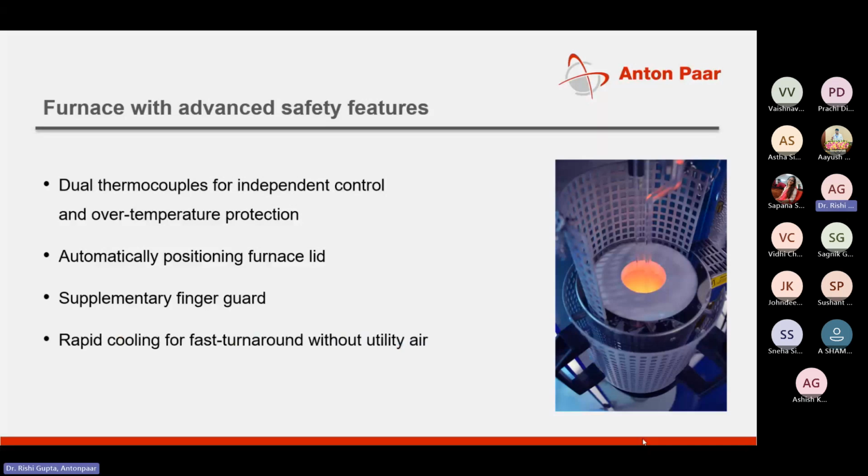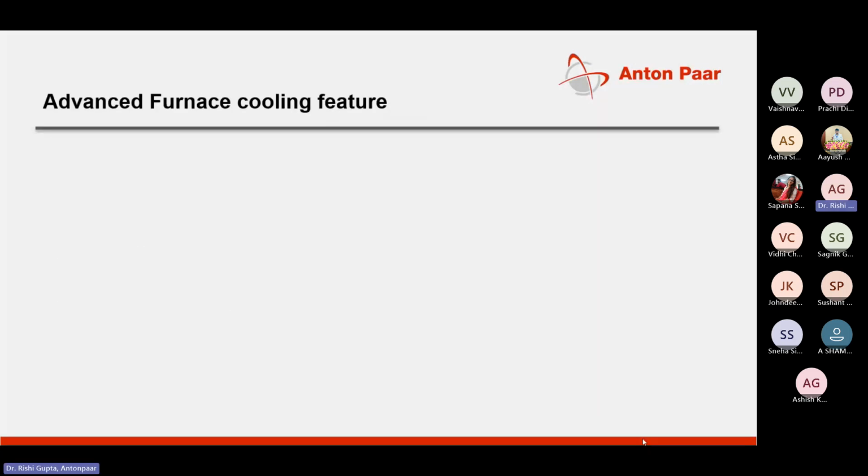The cooling air facility here in this case for Chemisorption is within the machine itself. At the base of it, where you keep the dewar, there is a flap, and if you remove this flap, you will find that there are vent holes over there, and these vent holes are basically for cooling the sample. We already have an inbuilt air cooling facility. So we have a fan over there which will cool your sample.